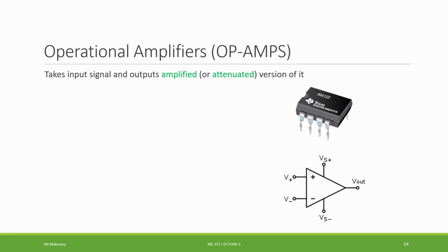The output voltage from the op-amp is lower than that of the input. Now, there are other purposes for using op-amps, but for this course, this is generally what we are going to be using them for. Op-amps are going to be put into a circuit whose greater purpose is in part to amplify or attenuate our signal, and these circuits that we create with op-amps could be inverting or non-inverting. So it's possible, like in an inverting circuit, that the polarity of the input signal is going to be reversed. If it comes in positive, the output will be negative, and again, vice versa.